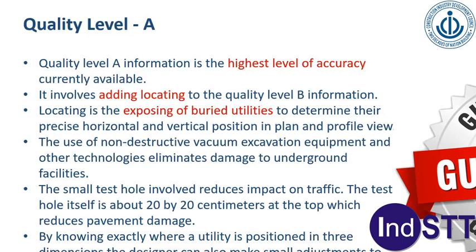So there are vacuum excavations, there are air vacuum excavation, there are water jet excavation, etc. We can also open the existing manholes and chambers. So this is one case. So this is, for example, power cable, then this is water pipeline, and this is the open chamber. So if you take the utility data using this also, it comes into quality level A. Again, you can have a video look at vacuum excavation, how it looks like. This is a very good video which is there. I have given a reference here.